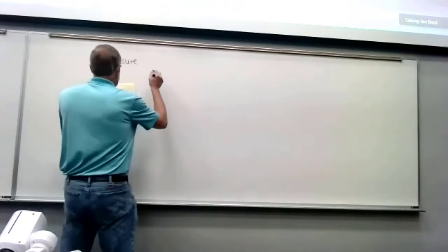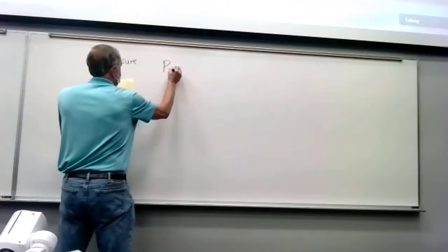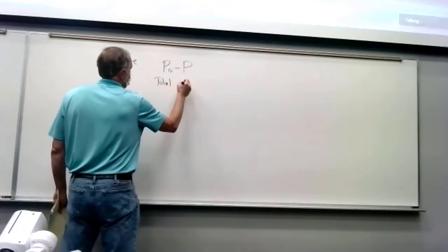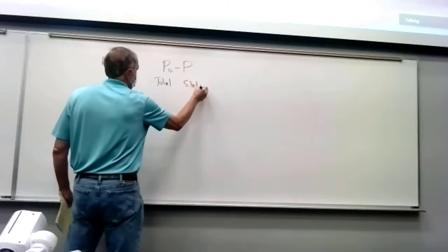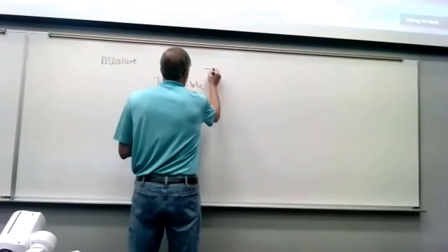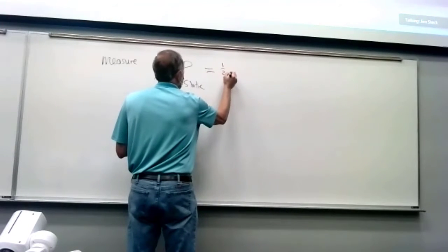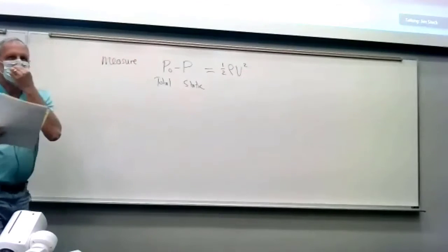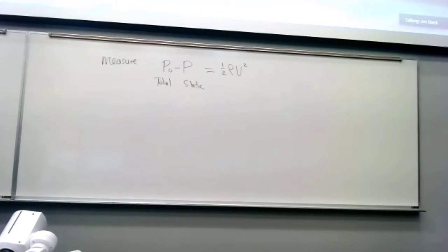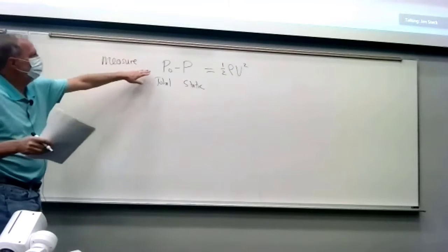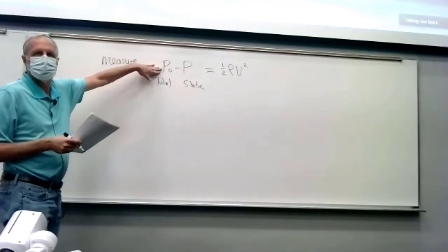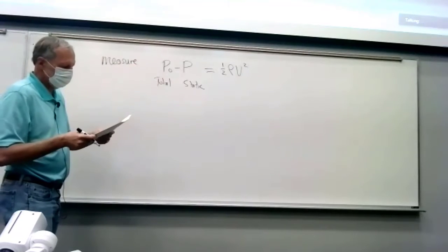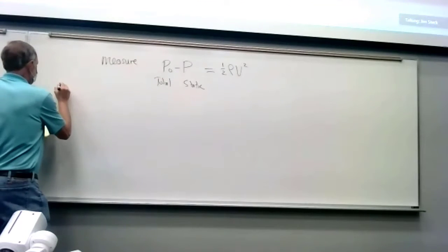So in this, we measured the difference, the total pressure and then the static, because through Bernoulli's equation, that's related to 1/2 v squared, and so we can calculate airspeed. That's because at p0, the velocity is 0, the flow has gone to 0, and so that difference is directly given to the velocity. So let's do an example.